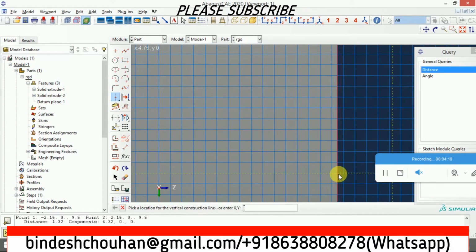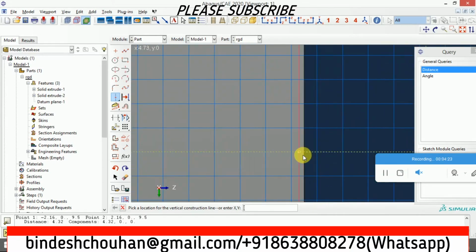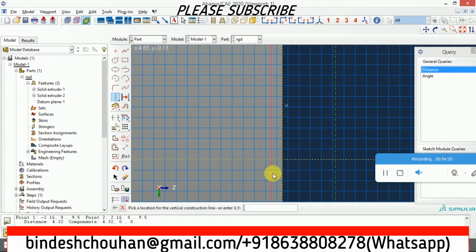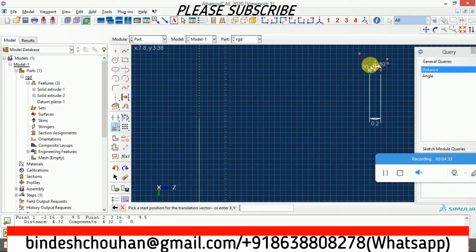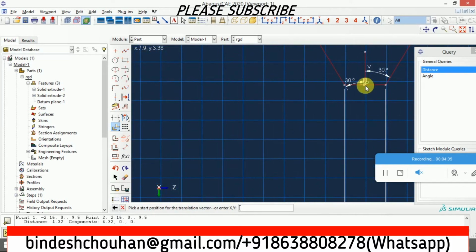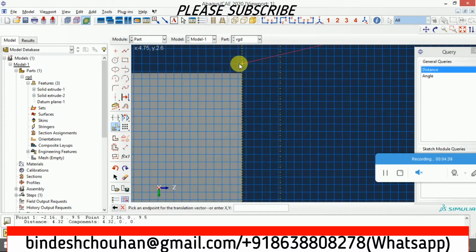The horizontal construction line should be there because it will be used as an axis of rotation. So this is the construction line I have selected. Now I'll move this arrangement. I'll take the center point of it and move it over this construction line.